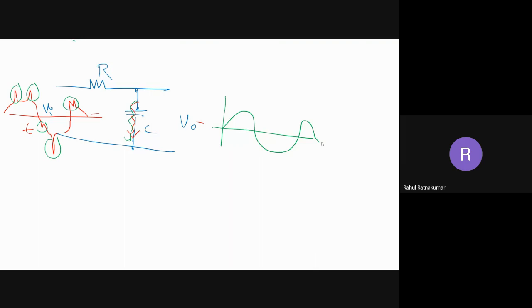The same concept with an op-amp gives a low pass filter. This is a low pass filter because high frequency is short circuited across the capacitor. This is the low pass filter output, LPF output. This is conceptually right, but if we use an op-amp, this works much better.